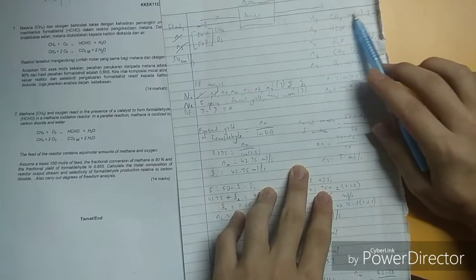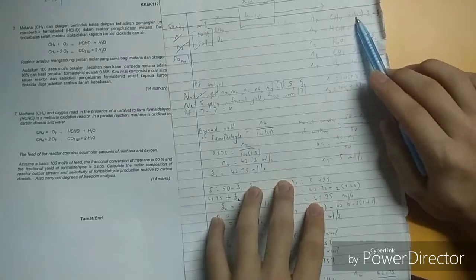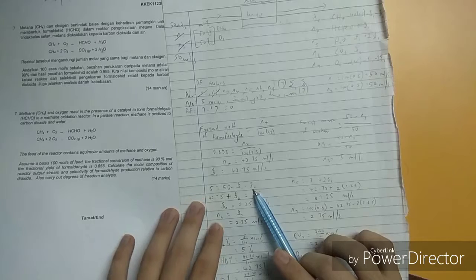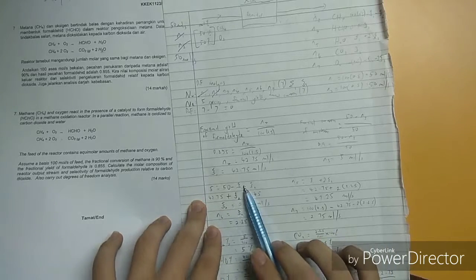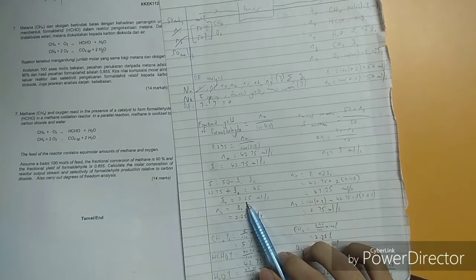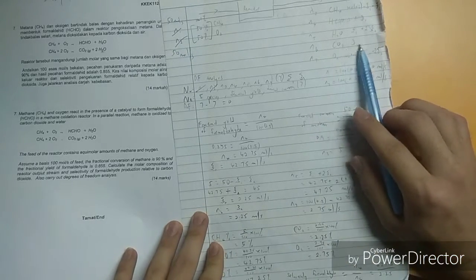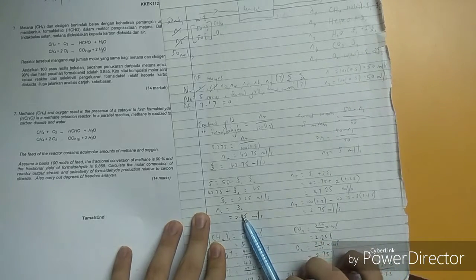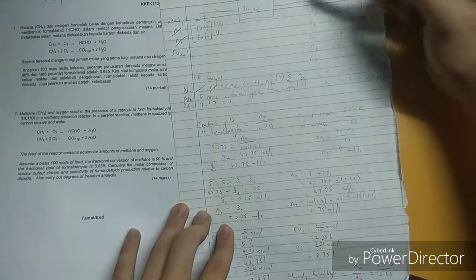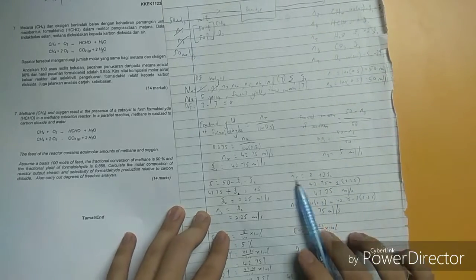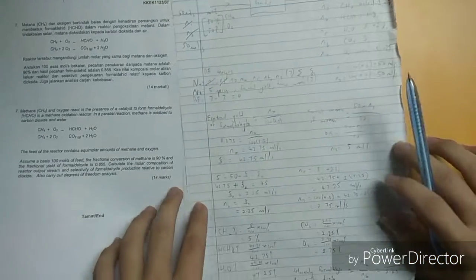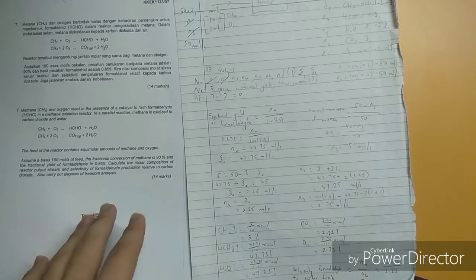Based on the equation, N3 equal to this one, and just substitute it inside this, and we can find C2. So C1 we already got 42.75, so we find C2 is 2.25, and based on this equation, C2 is also equal to N6, so N6 is also equal to C2. After we found C1 and C2, we can solve all these unknowns. So N5 equal to 47.25, and N7. All the unknowns are solved, so we can solve the questions.